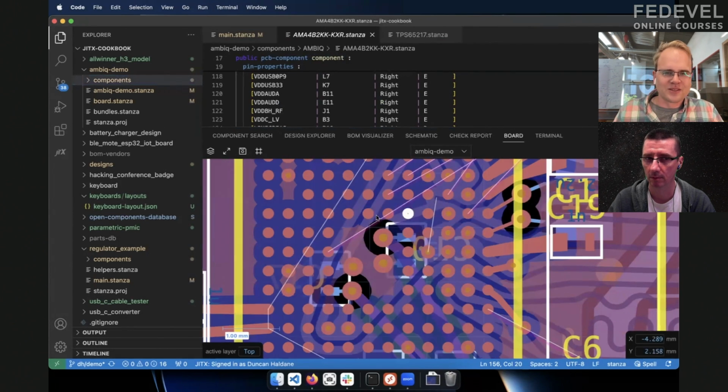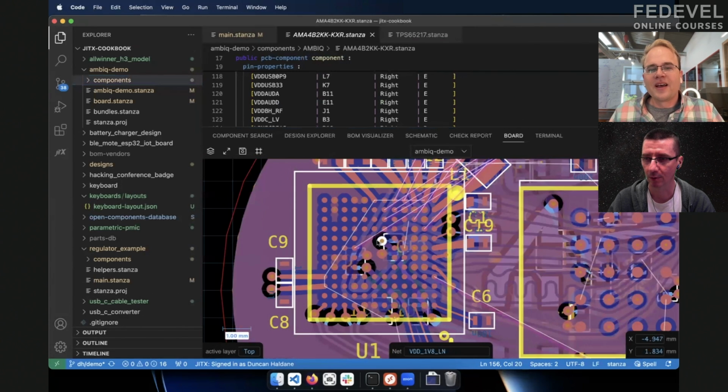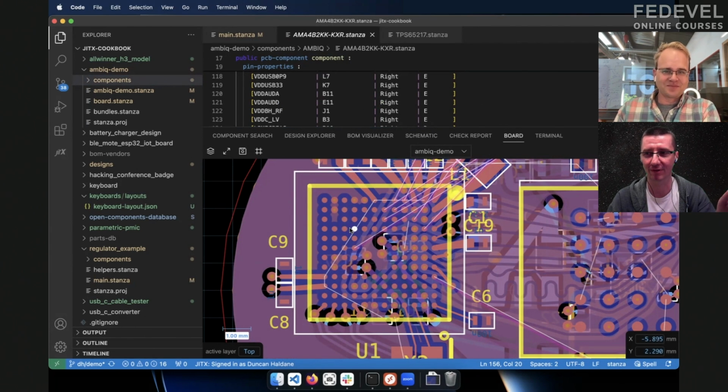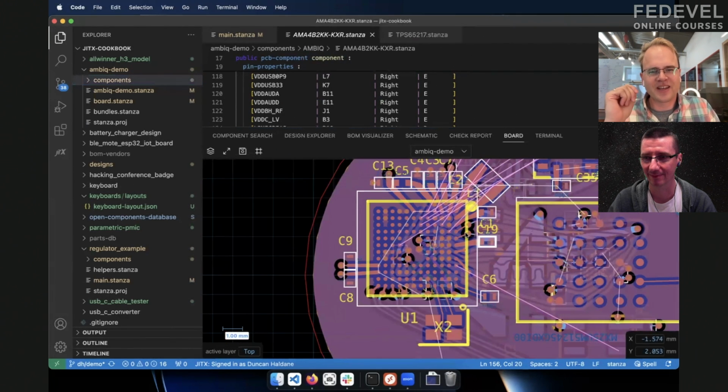So I've set this up as a test case for the auto router. This is the one you mentioned. The reference design is on 8 layers. That's right, because you can't really fan out from the 5th row without going inside of the PCB. So this one's got 4 layers, and I think I can do it. I haven't finished the design, obviously.